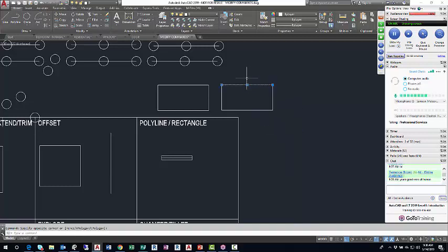If I click on the lines, you can see each line is a separate entity, and it would take really nothing to open up this shape. It says it's closed, but I can open it just by grip editing one portion. So the process of creating a polyline isn't different than the process of creating lines. The resulting object is different, and that's the difference there.